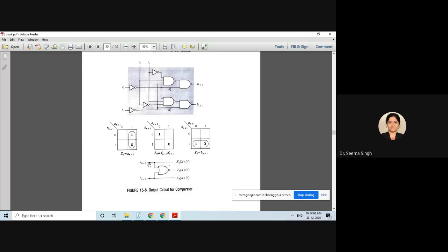What you can see is if Ai and Bi both are 0, 0 or 1, 1, then this XOR gate will give you high, showing that Z2 is high and X is equal to Y. And otherwise, if Ai+1 is giving you high, it means your X is less than Y, and if this is high, it means your Y is less than X. This we can do with general understanding, but without general understanding we can do it with a K-map also.